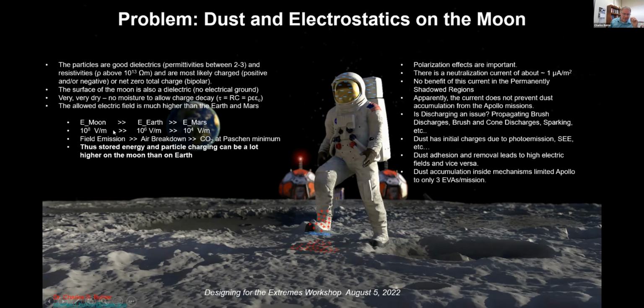So basically, electrons have to spontaneously overcome the work function of the metal to discharge. It's a little bit interesting though. The 100 times higher E field is a 10,000 times potential increase in the energy of that discharge because it goes as E squared. Something to think about if we are going to have discharges as two materials come in contact or two large structures come in contact. You might have to think about how you're going to minimize those potential differences because there could be charge at different levels based on tribocharging. I'll show a little example here with the astronaut walking.